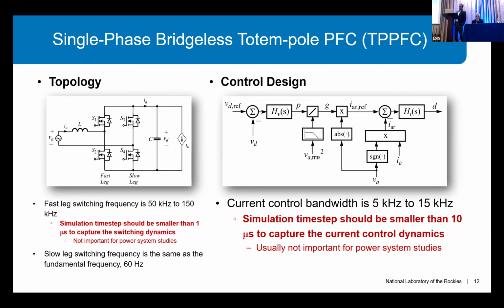So what this power supply unit does is it takes the single phase low voltage AC input from the IT rack and converts it into medium voltage DC bus level around 400 volts. And then there are other power electronics converters which take it down to low voltage DC of 50 volt DC. The control system has the DC bus voltage control and the current control.